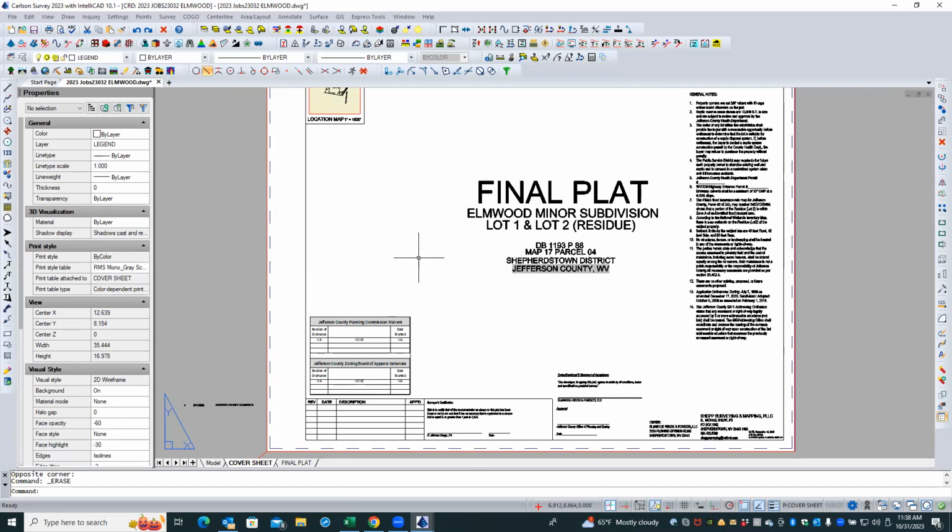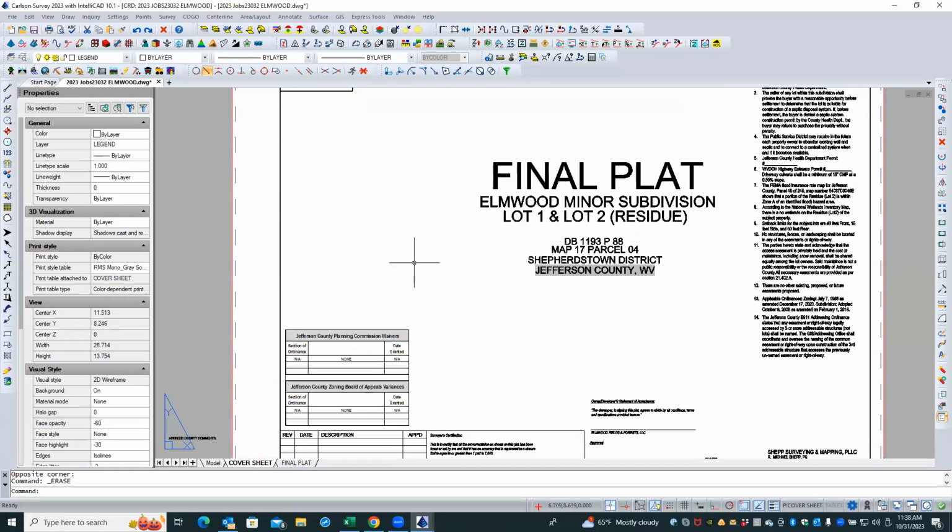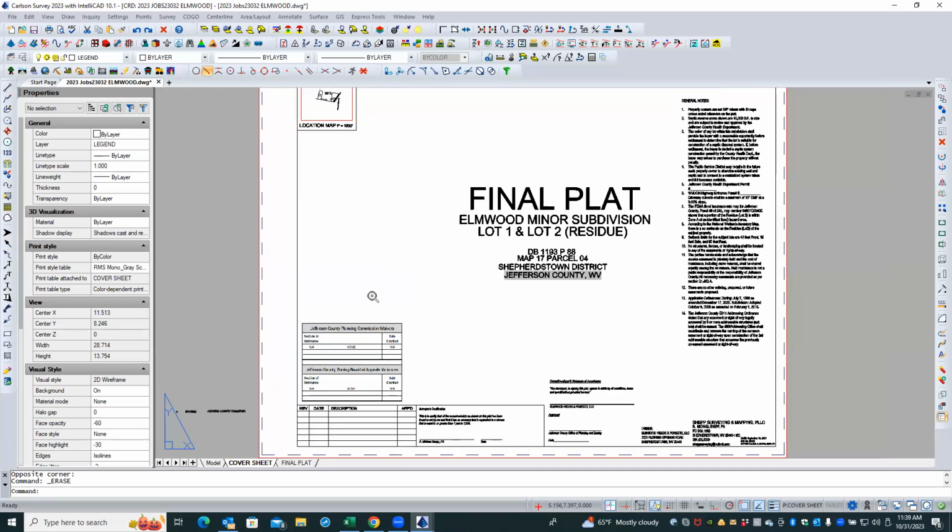You are aware, aren't you? I've noticed a couple times when you select things, you do realize that when you select a window and move it to the left, it's crossing, and if you move it to the right, it's enclosing. Are you aware of that? Yeah, I just don't do it right all the time. That's fine, we all are that way. I just want to make sure you knew that distinction. Sometimes it's easier to select by crossing, or you can keep from selecting things you'd have to deselect if you do it by enclosing. So there are just various ways. All good.